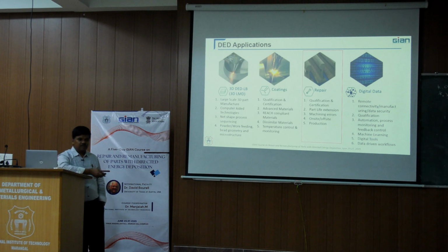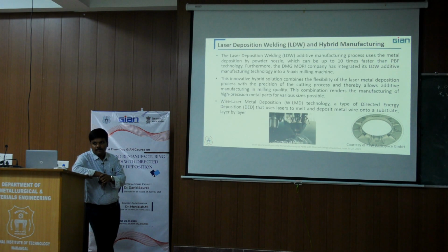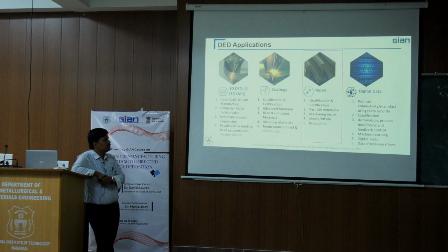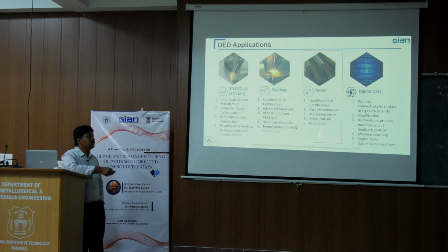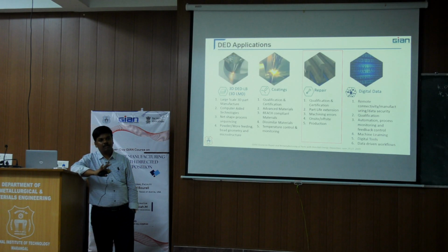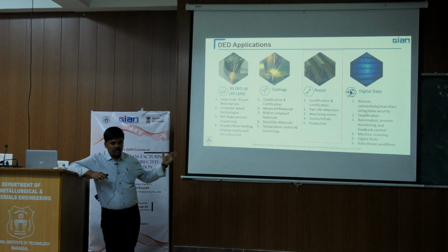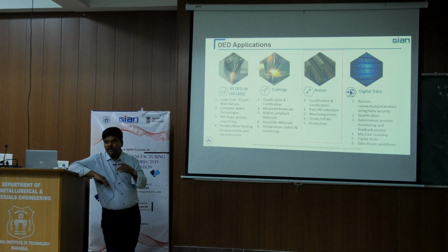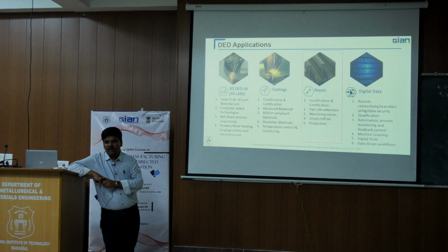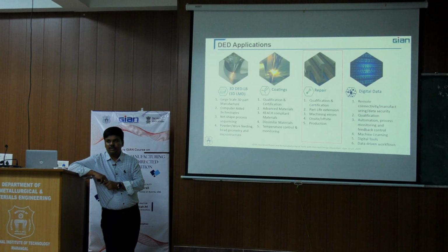And especially when I am talking about repairing, these are all additional features we are adding to the components. But when I talk about repairing, especially for large components, qualification and certification are important aspects. We can repair it, but will the repaired part have the same kind of mechanical properties and quality as the existing part? We can generate the data with a 3D scan and give the part plan for how we can fabricate it. But are we getting the same or better mechanical properties than the original part? That is where the challenges come.